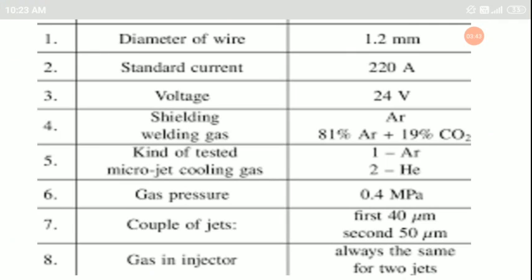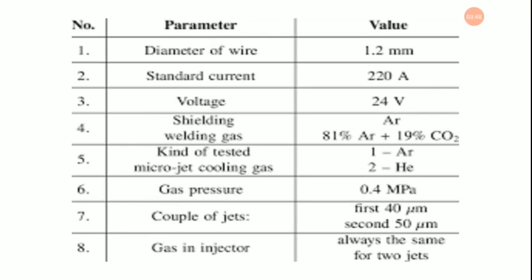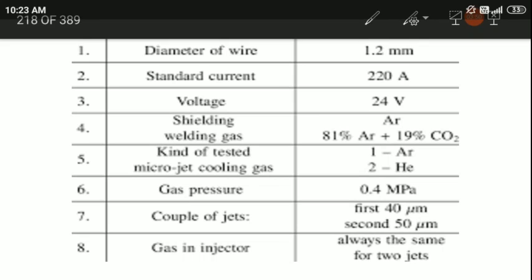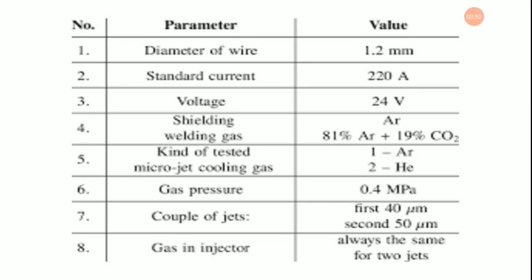So weld quality mainly depends in the field of welding on the mechanical properties of the weld metal zone, that is the WZ, and the heat affected zone, that is the HAZ, which consecutively is influenced by metallurgical uniqueness and chemical compositions of the weld.